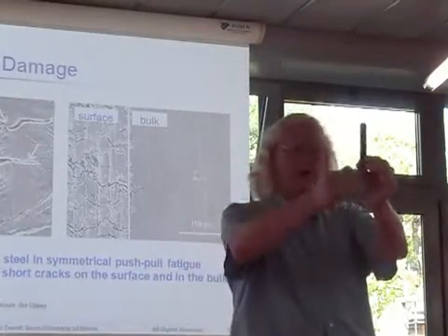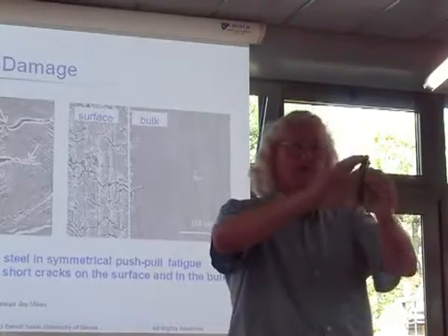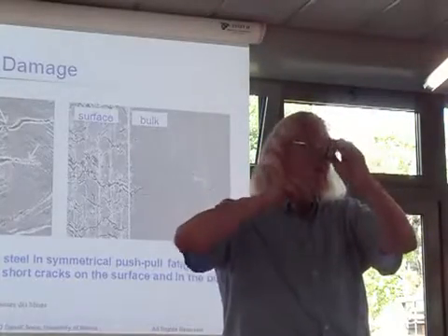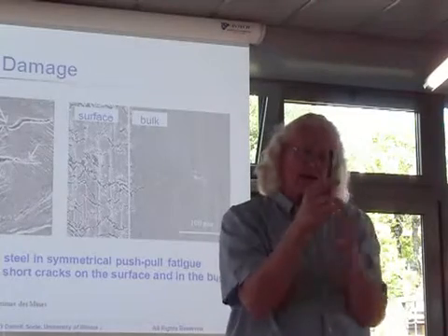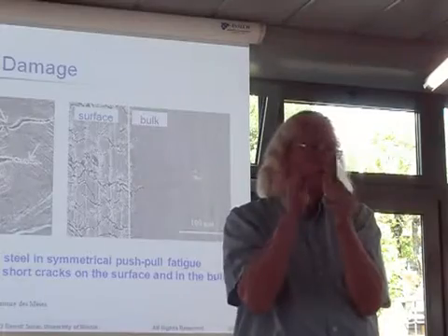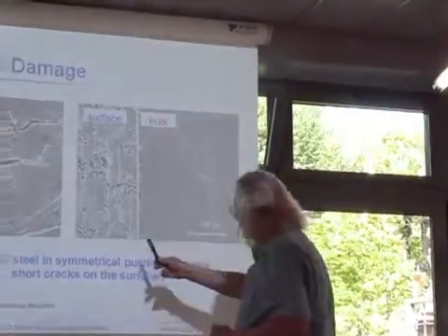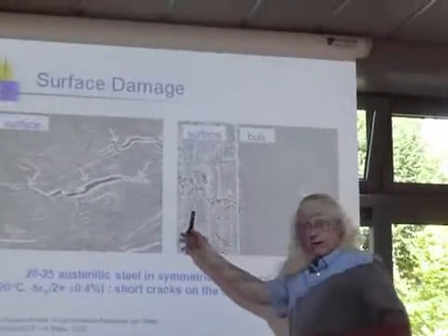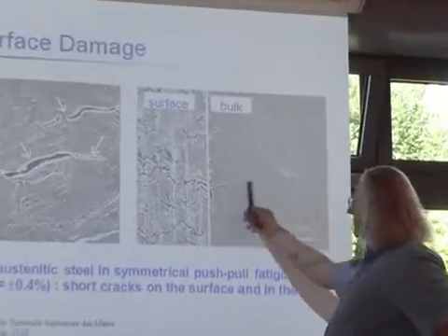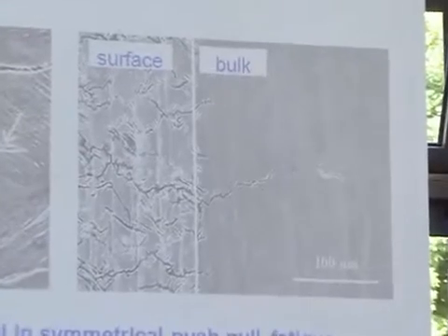You are right. I could have a 100 millimeter crack this way, and the bar would be just fine, either in tension or twisted or bending. To break this, I have to somehow grow the crack through the thickness. So I have to grow it into the depth. And you can see that even though I have all of this surface damage, very few of these cracks actually can grow into the depth. This is the important part, growing into the depth. It's the part I don't see.